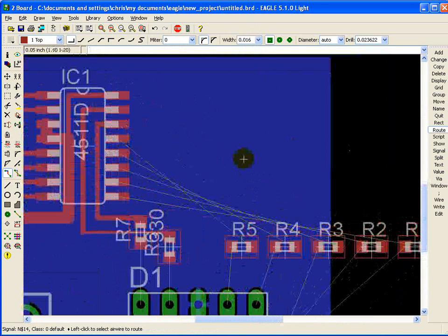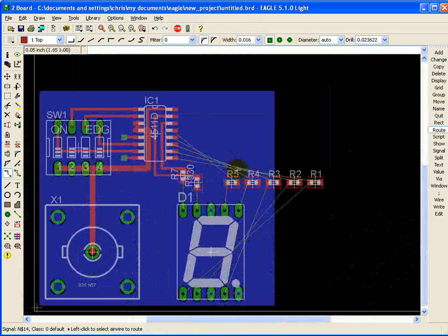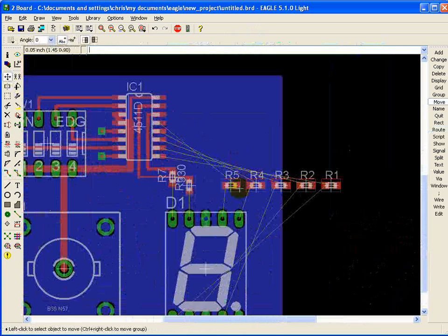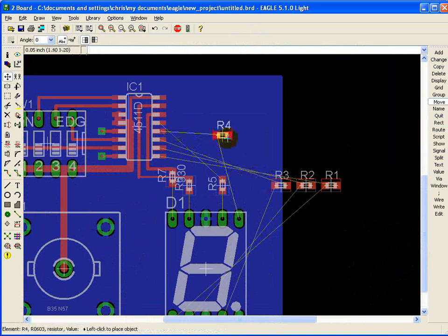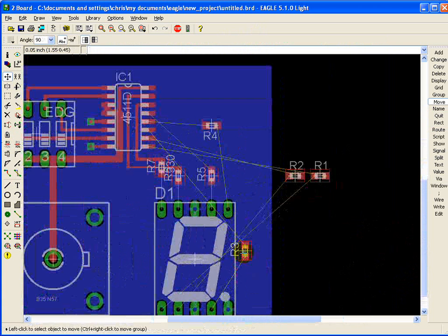manufacture the board. And one important thing to do is make sure you know the design rules of the PCB house you're going to use. You get what you pay for. If you want to pay a pile of money, you can do just about anything you want. If you want to go on the cheap, like most people do that use Eagle, you kind of have to play by their rules and make sure you got all your traces and all your vias the right size. That's how they manage to do it cheap. They limit their investment in drills and tips.